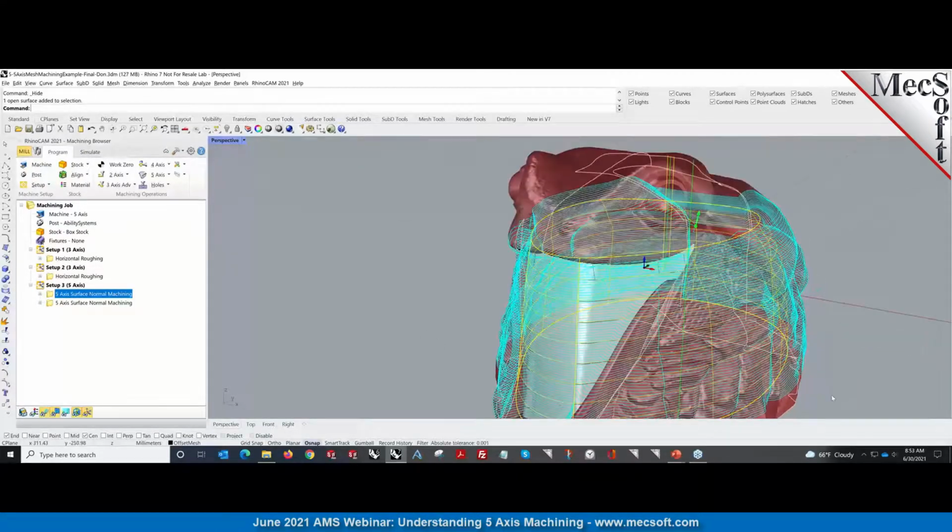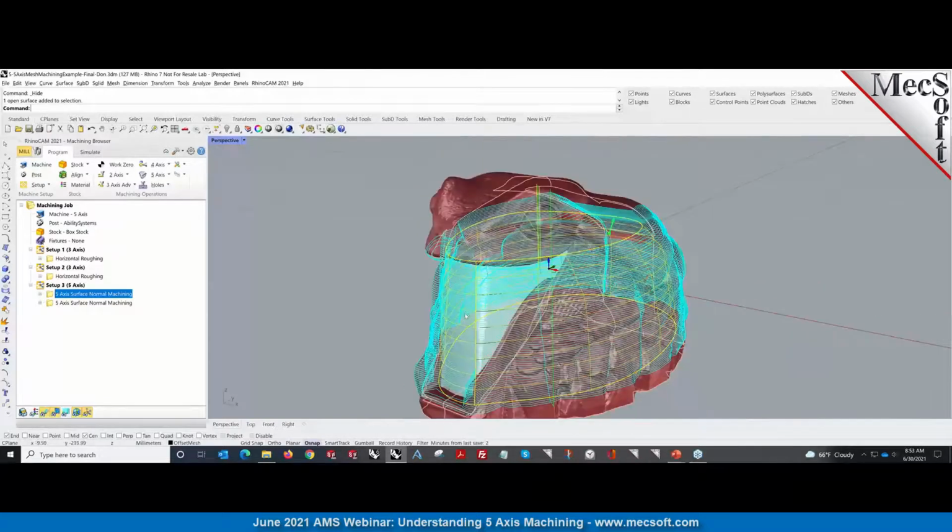And we had capped the holes. The nice thing about that, we had also capped the holes at the same time. Once we created that surface, we had capped it pretty nicely, so we were able to actually machine it. And then we created section curves going in the other direction to create that surface and to machine the top, actually.